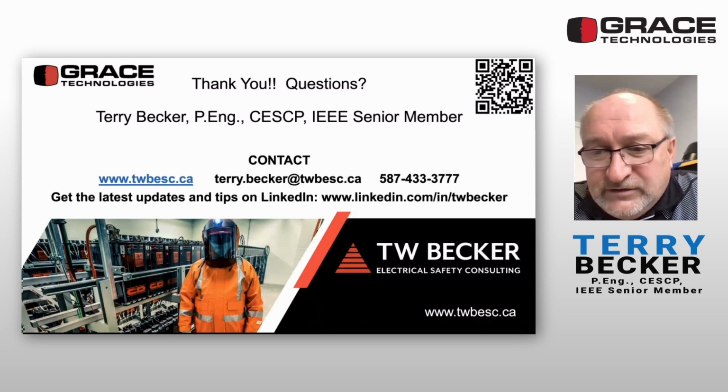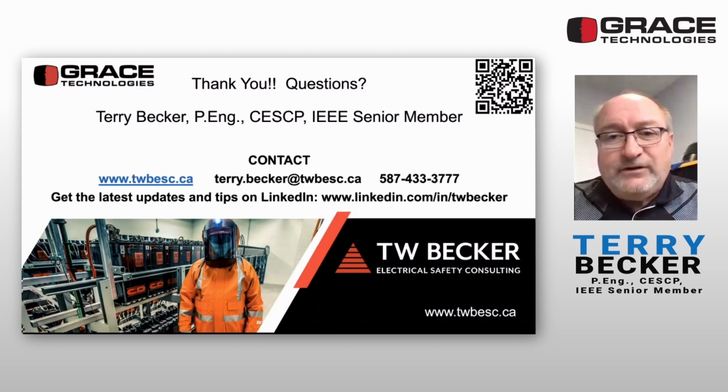Cintas makes ATPV 12.2, but does not make shirts at ATPV 12.2. The only option I see is one pullover shirt at 16, and ATPV 12 is the highest level I can use, with the standard hard hat and face shield. So this is an everyday task where you have to consider worker comfort. So shirt or pant, the shirt and pant will never be the same ATPVs, but if it's a coverall, it will be. So specify 8 to 12 coverall or shirt or pant, and then the pant will be a higher ATPV, the shirt will be less.